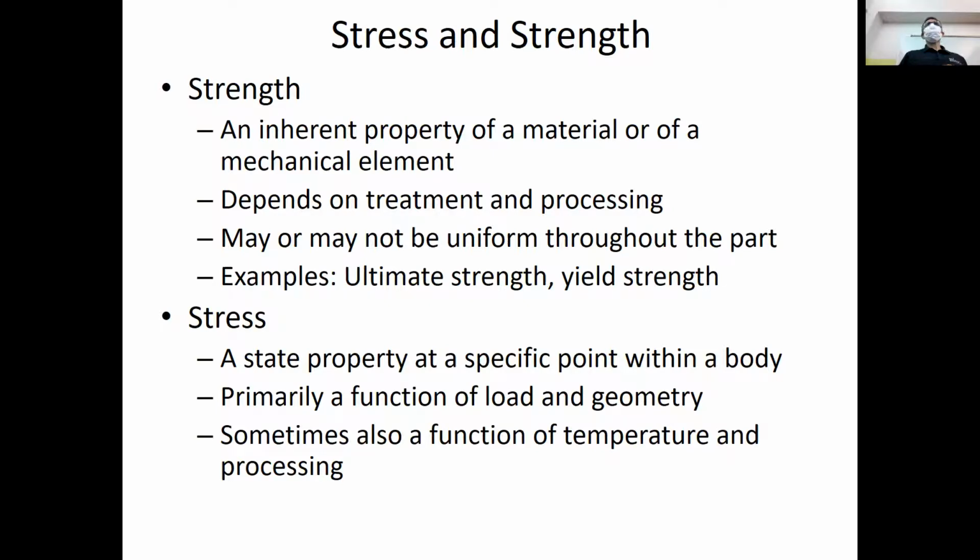And of course, we do not just run one simple test, but we run many of them, and then there is a statistical study before that strength is being reported. Like when you go in the back of the book and you pull the strengths, whether it's ultimate strength or yield strength of a material, this is not a result of one test, but this is based on a statistical study that comes up with this recommended strength value.